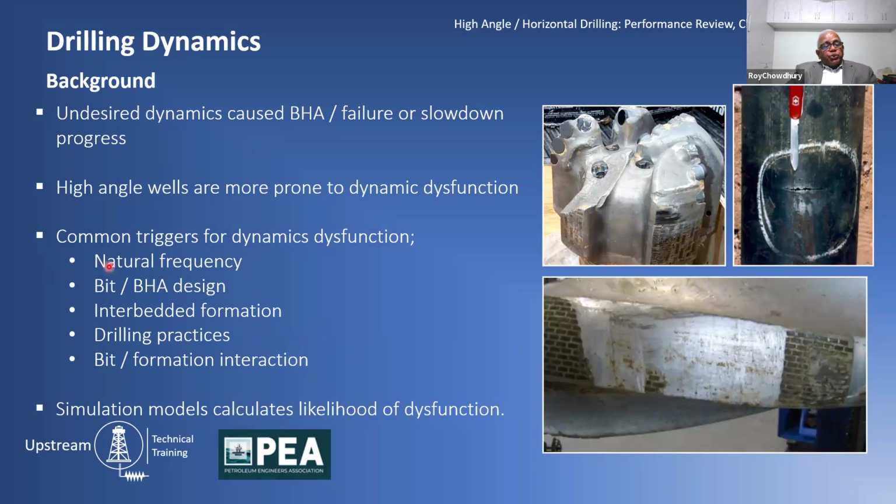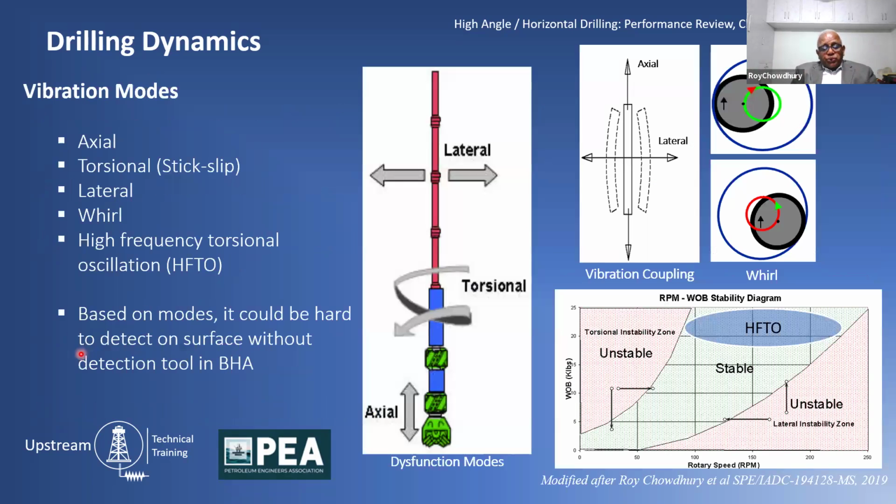Now, when it comes to natural frequency, good simulation models are available. These are computer-based simulation models that will often give you a parameter map, whereby, based on your drill string geometry and your trajectory angle, you can follow the safe drilling window and have smooth drilling. But that is not always true, though.